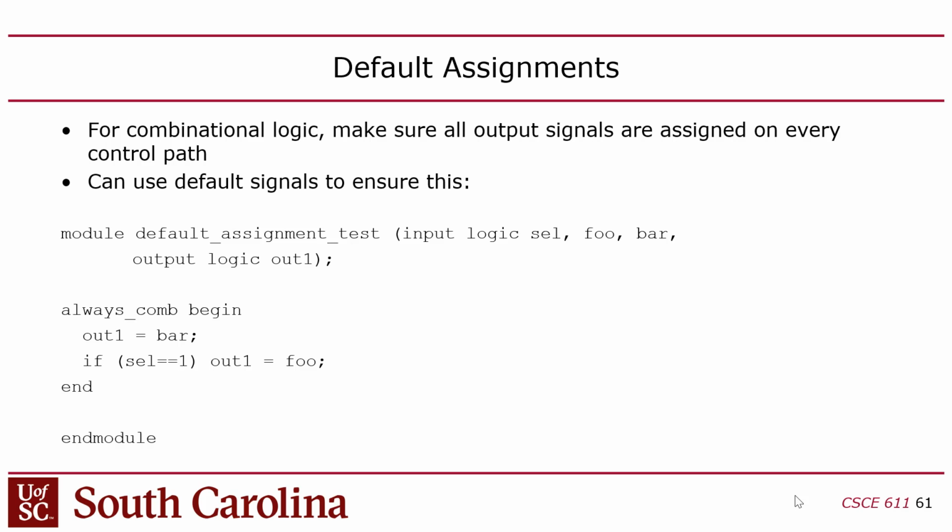Okay, so I just mentioned that. Okay, here's another example. Now here's one of the problems with always: what happens if the always activates because one of its inputs changes, but I don't set every possible output signal? In other words, remember that always is a circuit and it's driving everything that's assigned. You can have more than one output. So anything you assign in an always is an output. And the always is driving each of its outputs to VDD or ground, right? But what happens if I activate the always, but I don't set any of its outputs?